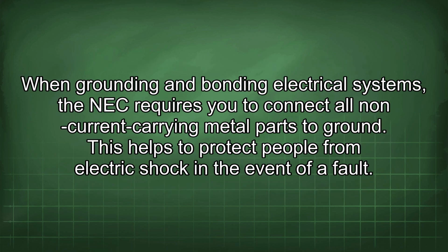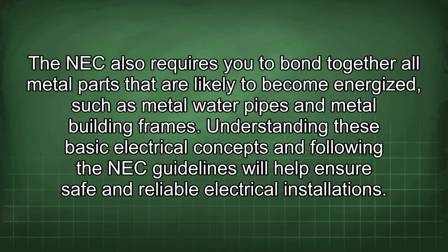When grounding and bonding electrical systems, the NEC requires you to connect all non-current carrying metal parts to ground. This helps to protect people from electric shock in the event of a fault. The NEC also requires you to bond together all metal parts that are likely to become energized, such as metal water pipes and metal building frames.